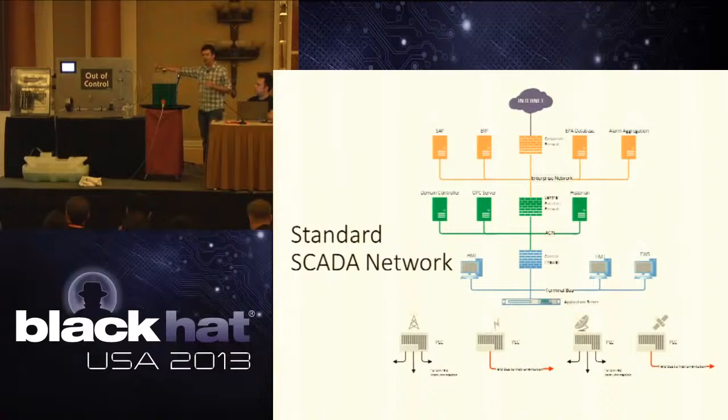And there's all different types of mediums that you use to connect that PLC up to the terminal bus, is what they call it. So that's how you get that data from the PLCs out in the field to the HMIs back at the control center. We showed some graphics here, but it can be anything from 900 megahertz radio, to microwave links, and it can be, of course, our favorite, a regular old cell modem that's given a public IP address.